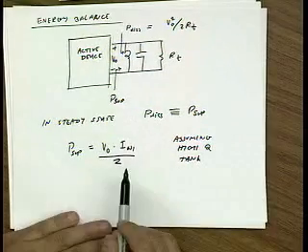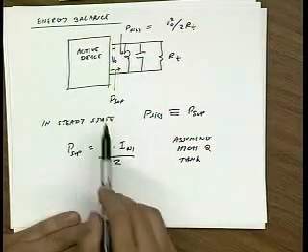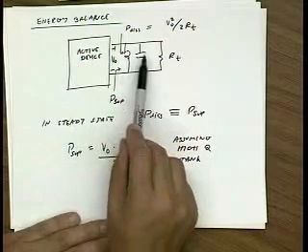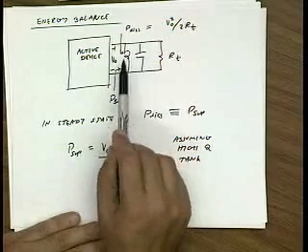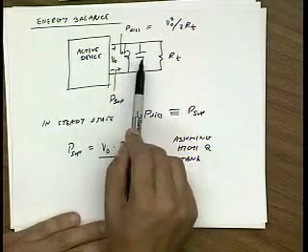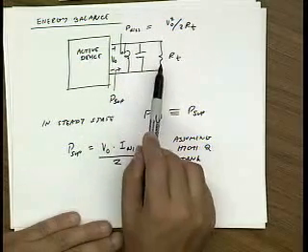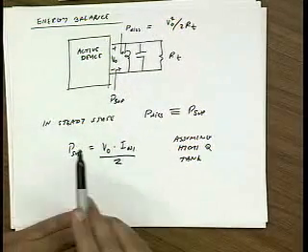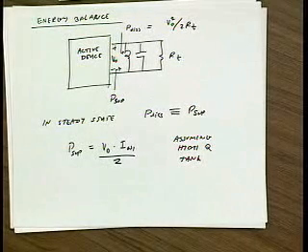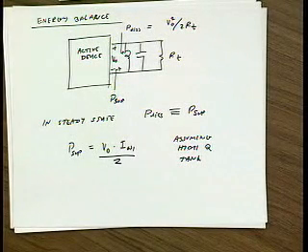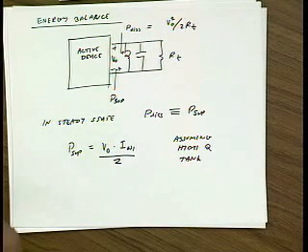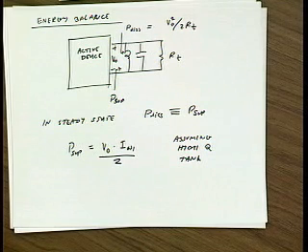In other words, the higher harmonics of this active device see this capacitance, and that's reactive energy. So they're not actually supplying energy to the tank. We're assuming that the only energy being supplied to the tank is from the first harmonic. Now this assumption is very close to what we said last lecture when we assumed that the output was sinusoidal, and we used the concept of the large signal GM. Any questions up to here?